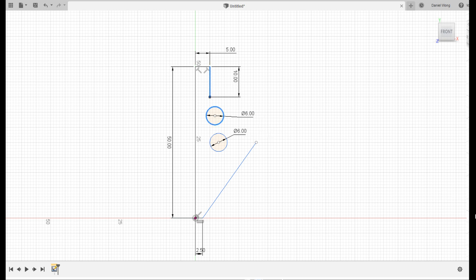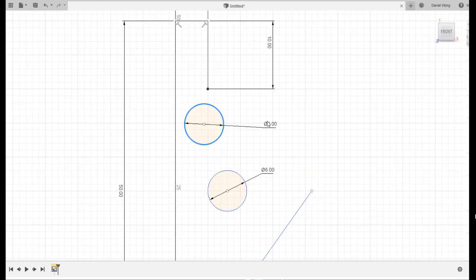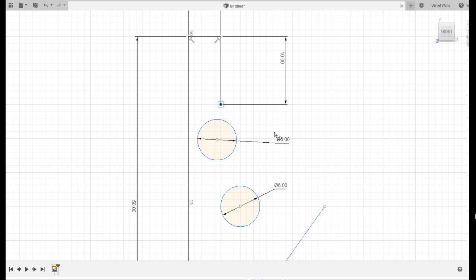So, you make those two coincident, or you draw those up, line it up. And what I might do in this case is create a line, make this line here 3 millimeters, and then make this line construction, and then hook my circle onto that. Does everyone see that? What I've done is draw a construction line to vertically align my circle, and I've done that arbitrarily so that I can trim the rest of this bit off.